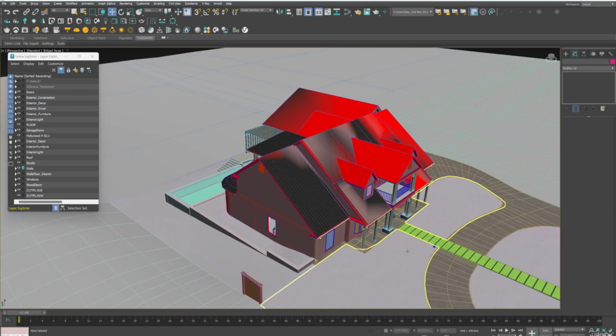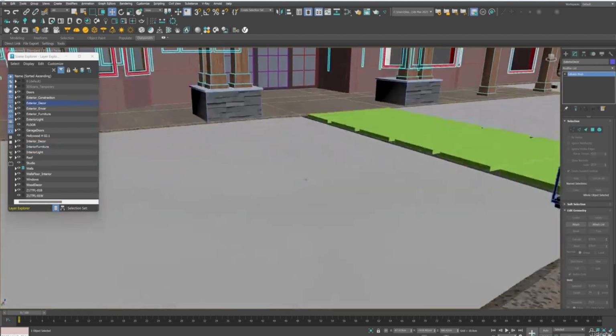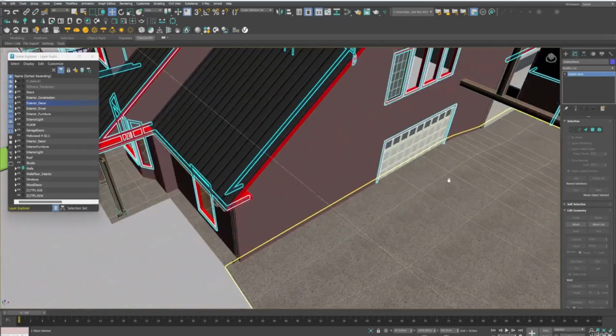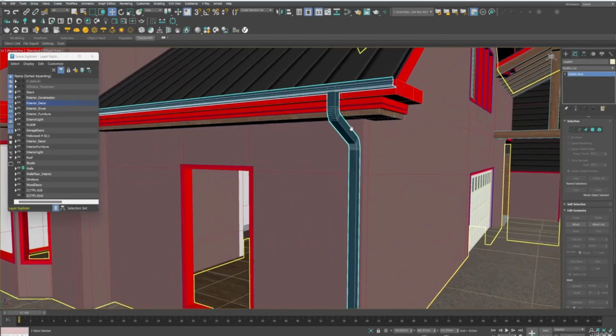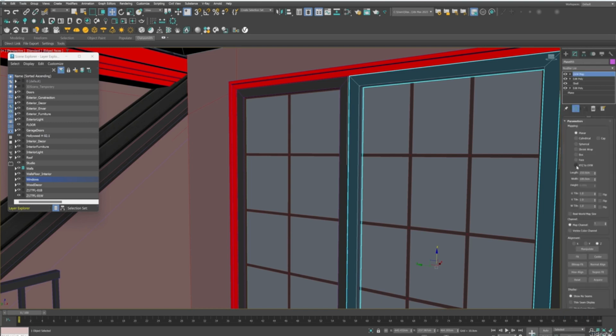Almost all elements of the scene are textured with the UVW Map modifier in box mode. The value of all sides is 100 or 200 centimeters. This is a quick method of texture mapping simple geometry objects, such as roof, windows, walls or columns. The UVW Map modifier is also applied to all painted objects or metal objects. This is necessary for the roughness map to display correctly.